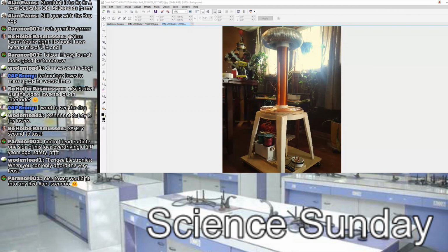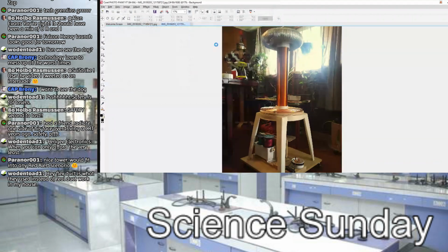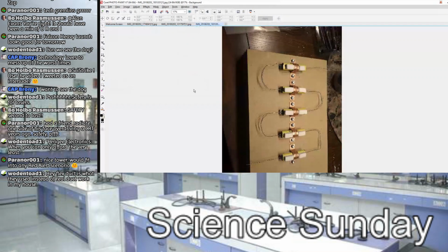I'm having a world of headaches with those capacitors we bought. Yeah, I mean, they're obviously of decent quality. I'm running them with the series being only 2, so really it's only rated for about 20,000 volts, and you're supposed to operate at about half. I'm not. They're charging to a full 20,000 based on the spark.